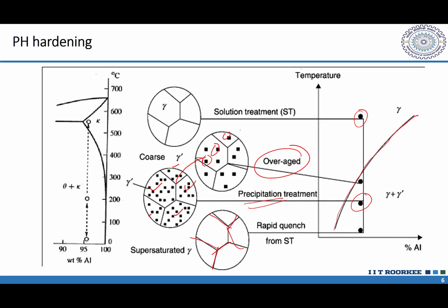The solution treatment, rapid quenching or supersaturated solid solution formation, and thereafter peak hardening leading to the fine precipitates, and finally the coarsening on the overaging.